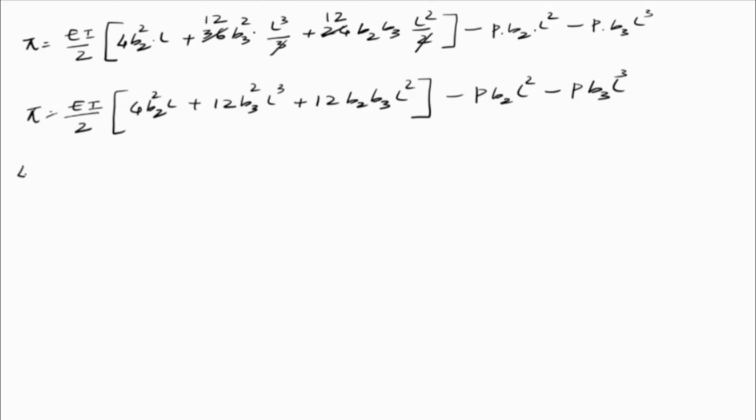Now I'll go with the fourth step, that is minimize P. You minimize the P function. Now once again, to minimize P function, which are the two constants? I have b2 and b3. Therefore, I have to differentiate this P function with respect to b2 first and equate it to 0. Similarly, the same P function I have to differentiate with respect to b3 and equate it to 0. So I'll get two equilibrium equations, solve those two equations to get the value of b2 and b3. Substitute these values of b2 and b3 in b1 equation. Okay, so I'll do that.